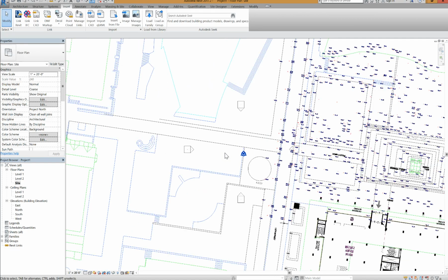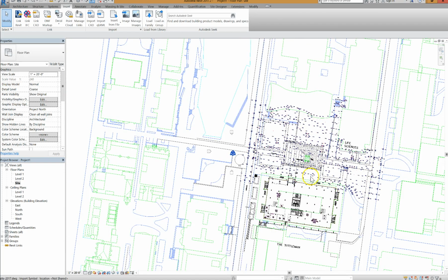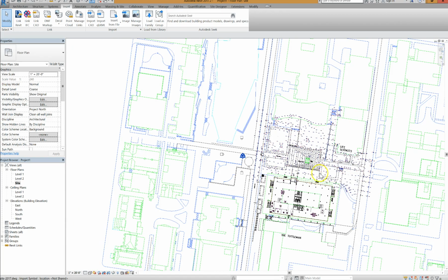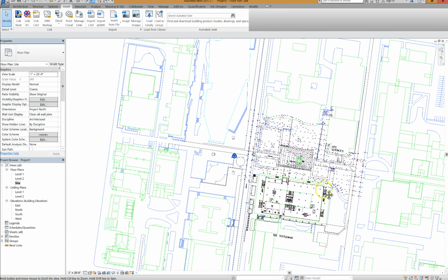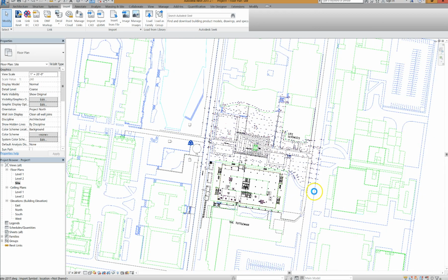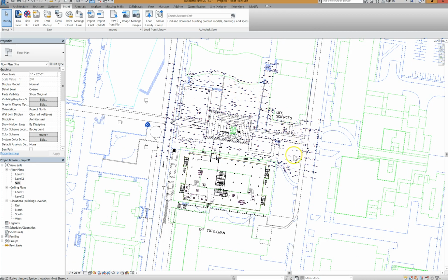Alright, so a few things. I know Bob's searched long and hard for topographic information. However, the only thing we can really find is an as-built around the bell tower. So really only one half of the building will have accurate topography. This is okay because we can always adjust. If we get more information of the other sides of the building, we can always add more data points into the Topo Surface in Revit.